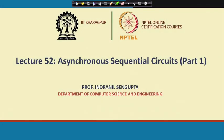In this lecture, we start our discussion on asynchronous sequential circuits. You see, the kind of sequential circuits that we have discussed so far is basically synchronous in nature. What is meant by synchronous? There is a clock, and all operations in the circuit are carried out in synchronism with the clock.